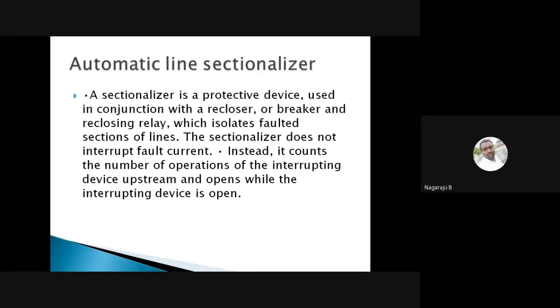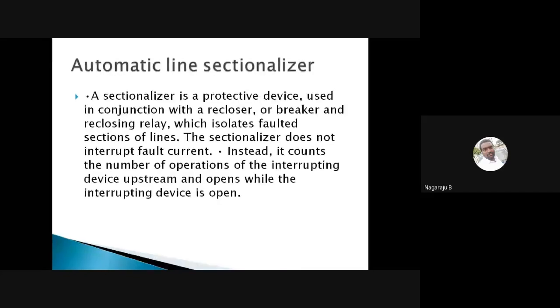So whenever the fault is cleared when the reclosing device is open, okay, I am using a recloser, the recloser is going to open, and the sectionalizer counter will reset to its normal position after the circuit is reclosed.